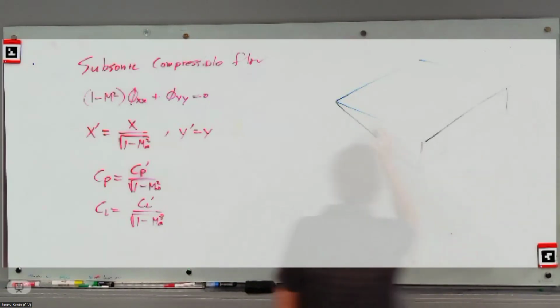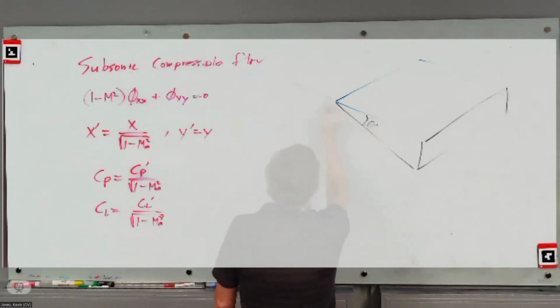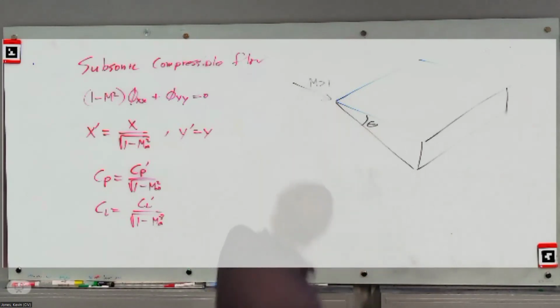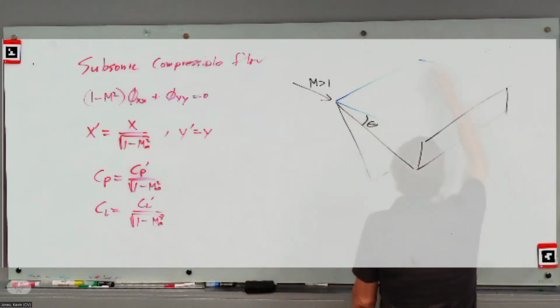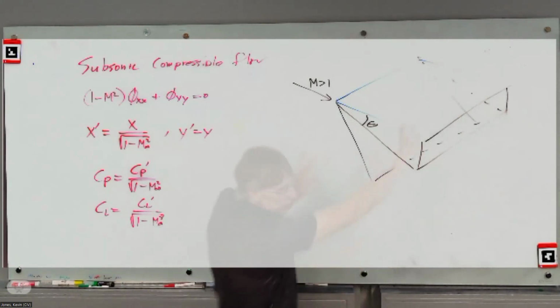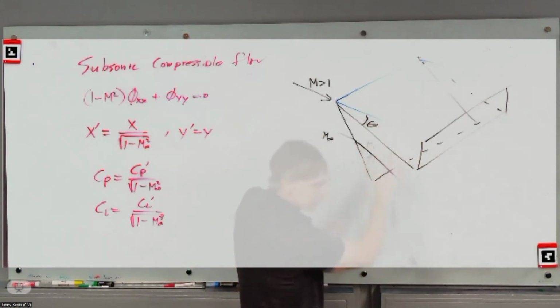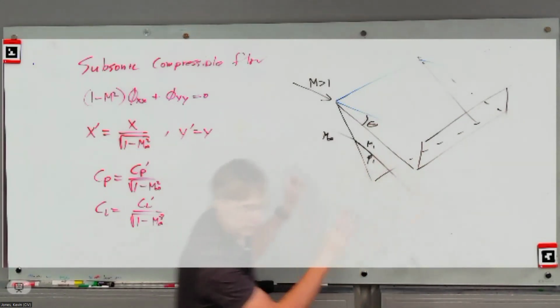3D version of a wedge, theta, arc. And so we're going to get bow shock comes off of this. But it's 2D, just stretched, extruded. So the flow under here, it's all constant value, right? Streamline that comes in, parallel to the surface. Here we have Mach infinity on here, Mach 1 pressure. Everything's fixed. They're just like you've been doing with the Pascal calculator.